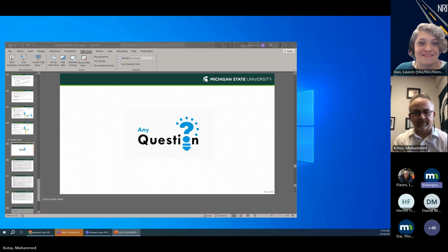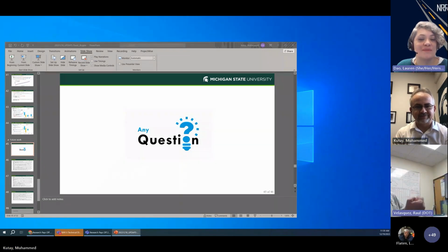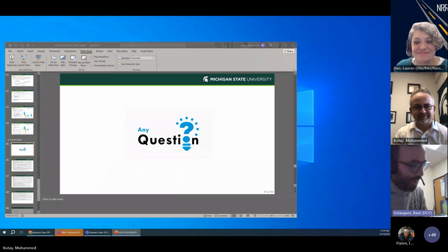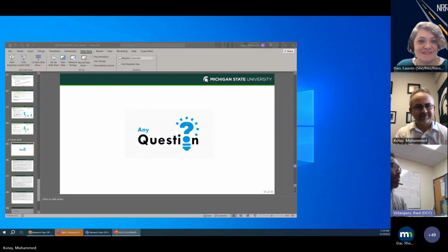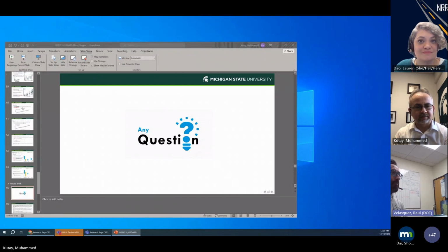Maybe I have a question, Lauren. Oh, okay, go ahead. Very good presentation. Thank you for giving an overview of this network level tool that we can use as DOT. Question about the last few slides. Basically the message I got was that if you build thicker asphalt pavement, then you will take care of your flooding. That makes me a little bit nervous because if you don't have a good foundation, I don't know if that's totally a true statement.